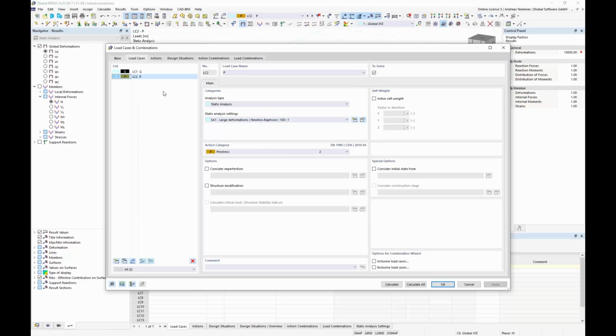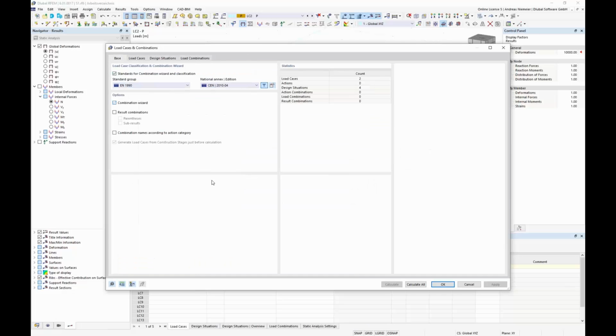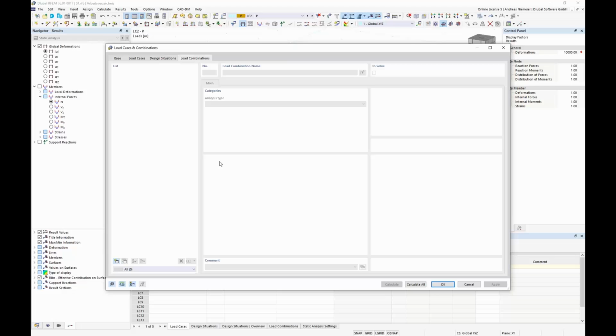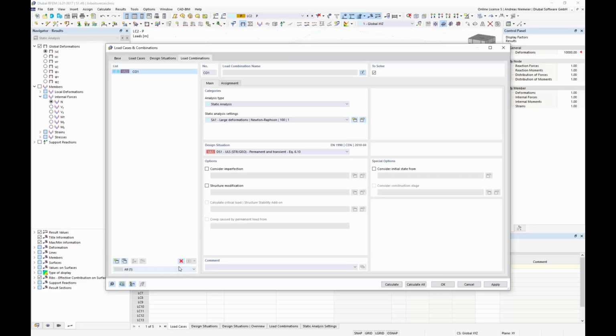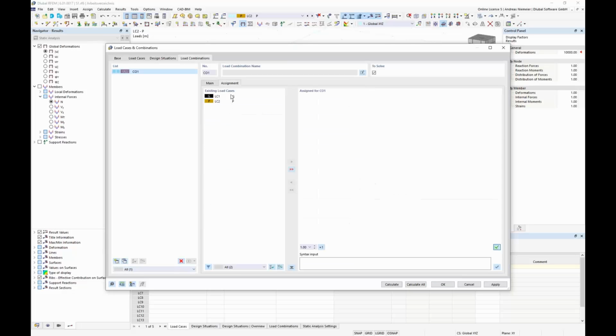For this, I deactivated first the wizard and go to the load combination and say, please combine form finding with self-weight. This means now for the program, because this combination 1 contains only this form finding pre-stress load case and any other load case, that this is a form finding job for him.